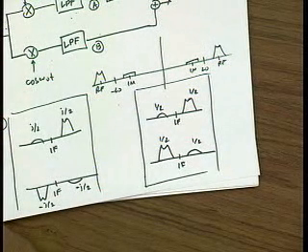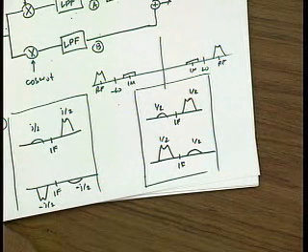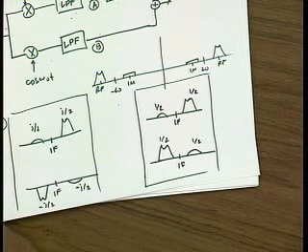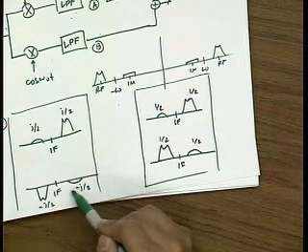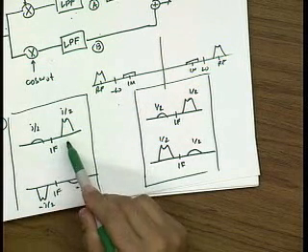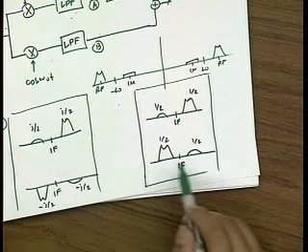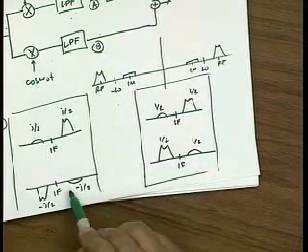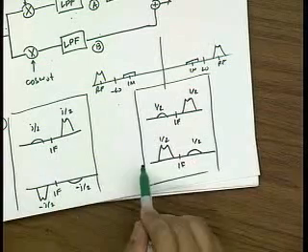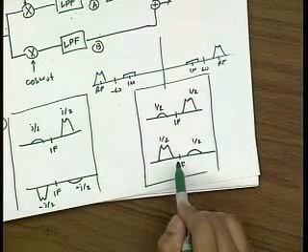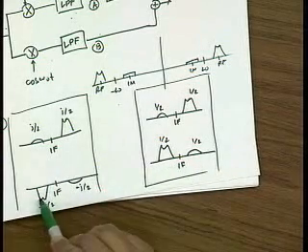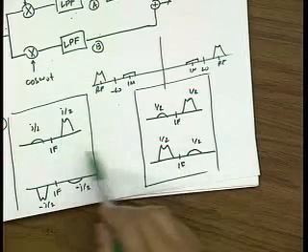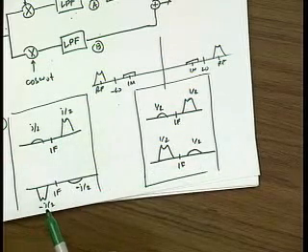Now we begin to see how we might possibly perform image rejection. Right now, this is the image term on top here that we'd like to get rid of. You can see here the image term is actually out of phase. So if I sum these two signals together, this image term would cancel out, but then so would the signal term. If I sum these directly, the signals will cancel out.